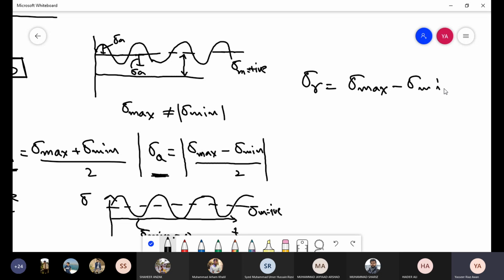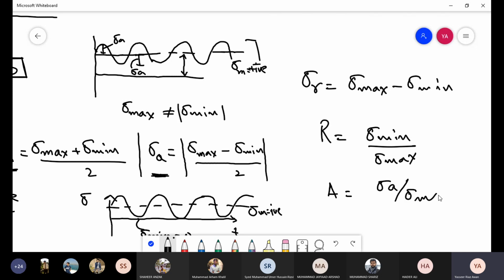So this is the total from sigma max to sigma min, ठीक है। इसी तरह स्ट्रेस रेशियो है, ठीक है, सो दैट इज सिग्मा मिन डिवाइड बाय सिग्मा मैक्स, ठीक है। यू हैव द एम्पलीट्यूड रेशियो, ठीक है, दैट इज सिग्मा ए बाय सिग्मा एम, ठीक है। सो दीज आर सम ऑफ द टर्म्स, for example amplitude ratio, you can say if the ratio is high, that means that the alternating component is dominating the stresses.